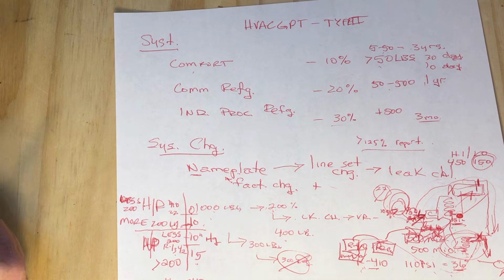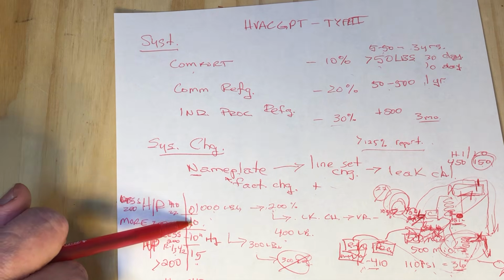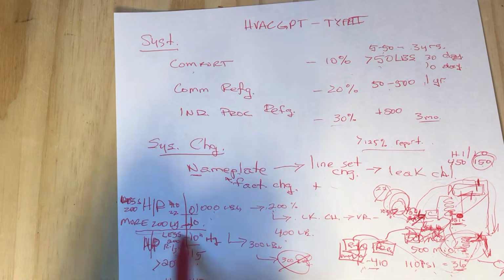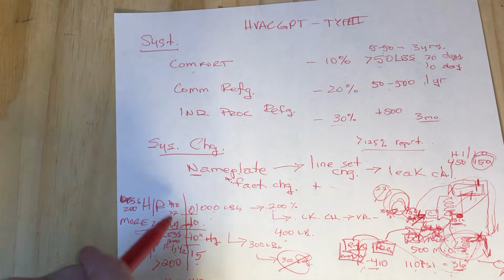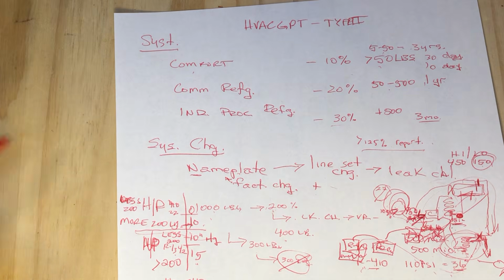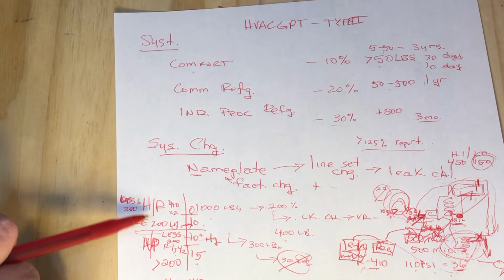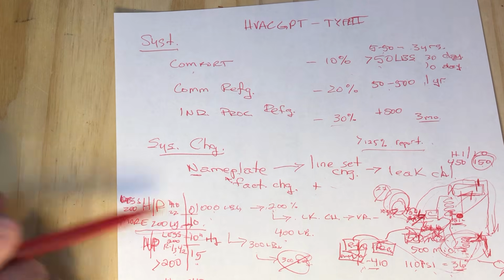And that's one of the big things they're talking about with this chart of 0, 10, 10, 15. Just remember the top two are going to be the high pressure refrigerants, which you know 410A is, and then the ones on the bottom will be the others. You can use ESCO's PT chart if you're taking the ESCO certification exam. On the PT chart that you use for the exam, one side is all low and medium pressure refrigerants and the other side is high pressure refrigerants. So depending on what side of the PT chart you're looking at will tell you what classification you're going to go into for the vacuum rates.